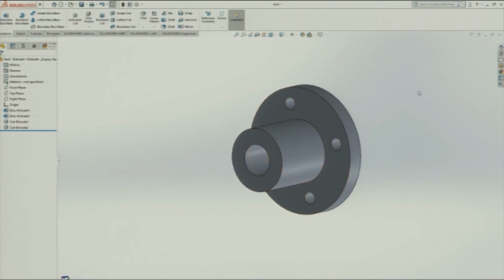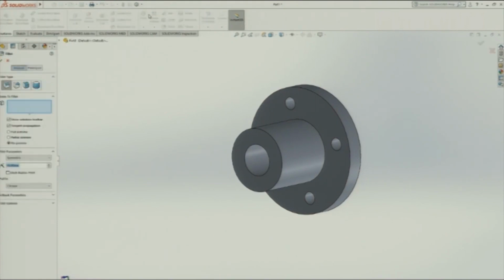Now, it is almost ready, but the only thing that we need to take care of now is the fillet part, to make the corners smooth, the edges smooth here. So, constant size, variable size fillet, again the fillets that we have discussed before are here, the full round fillet. So, let me put constant size fillet here.